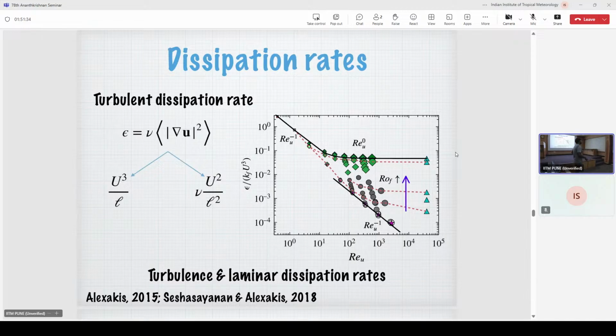But eventually, if you want particularly large Reynolds number, you should go to the turbulent regime, which is constant. But what we are trying to show later on is that there could be intermediate regimes where it could be more 2D turbulence than 3D turbulence. So it actually depends on the combined Reynolds-Rossby parameter. It sets which kind of flow you are in.